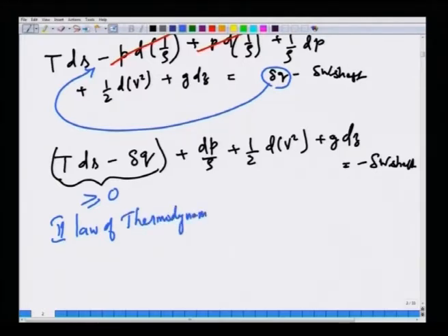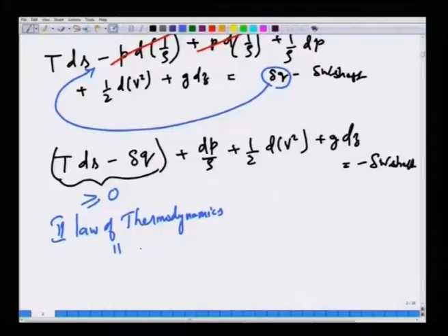Therefore, this is basically the amount of work that is lost irreversibly to heat, and this equality is valid only for a reversible process. But in engineering applications involving flow, you do not do them infinitesimally slowly over a sequence of equilibrium states. So, they are irreversible processes. Therefore, the second law of thermodynamics tells us that this is greater than 0 for flow applications.